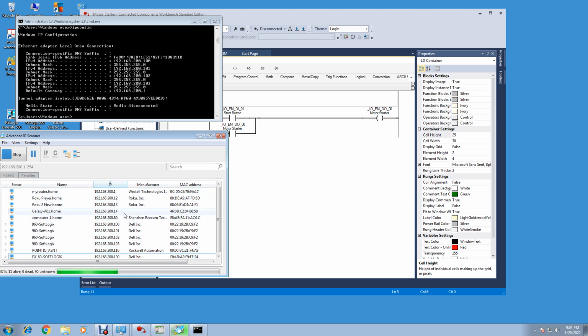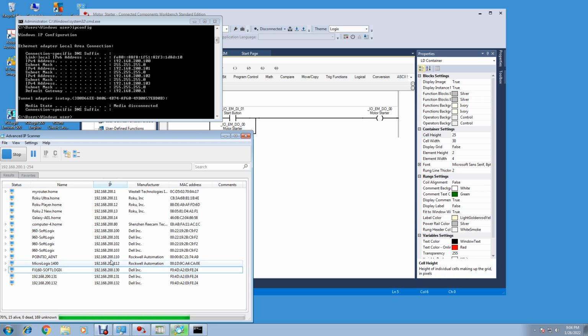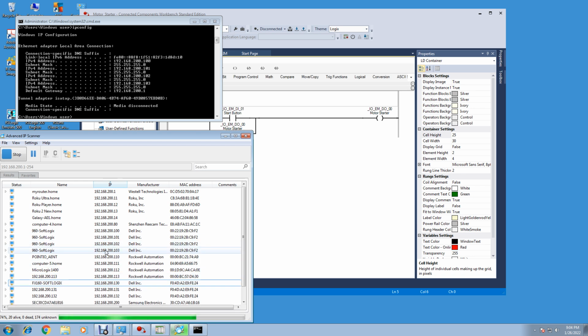And it starts up there, and it changed. And notice the 16's gone. And now I got SoftLogics as 100, 101, 102, and 103. We've added these addresses in here. Okay, so we're good to go, and we see we're clear. There's no conflict. That's why you can use this to find out if it's communicating to a piece of equipment, if you can see it, and make sure there's no address conflicts.